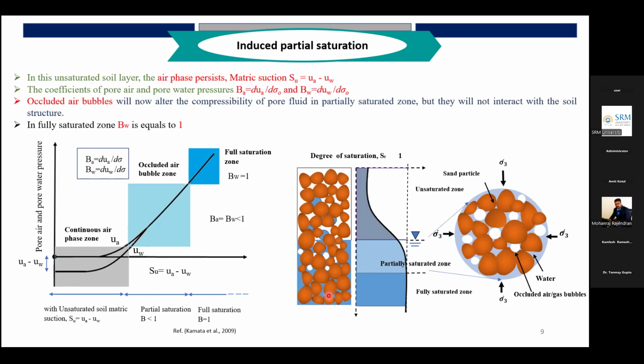Since the time is very short, we are talking about fine silty sandy soil. The developed pore pressure dissipation will not take place instantly. So your pore pressure is lifting the particles, and thereby your soil shear strength is lost. So the advantage of having accumulated air bubbles is that they will act as a cushion effect.